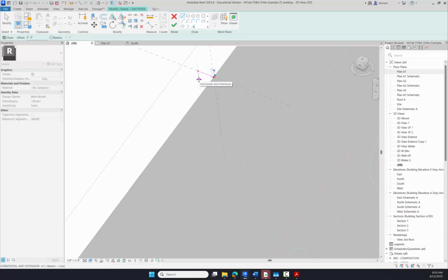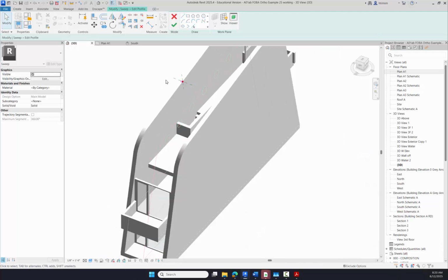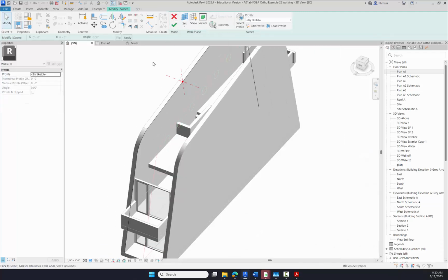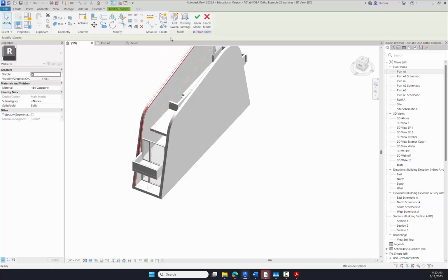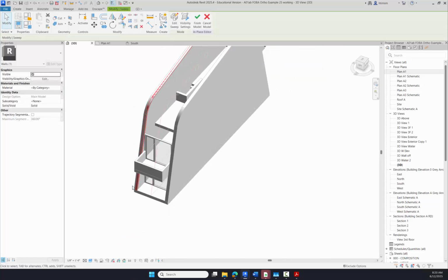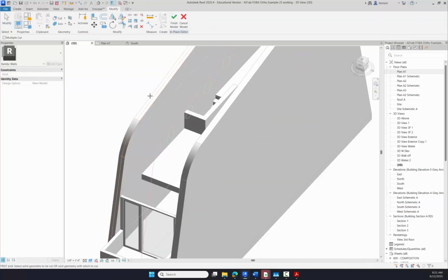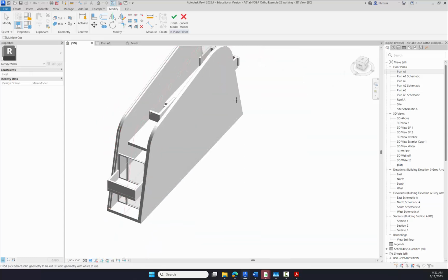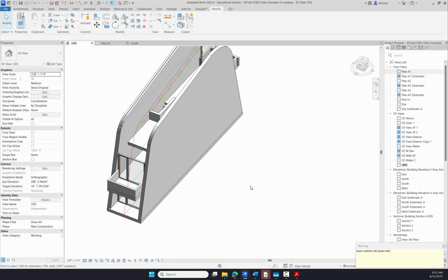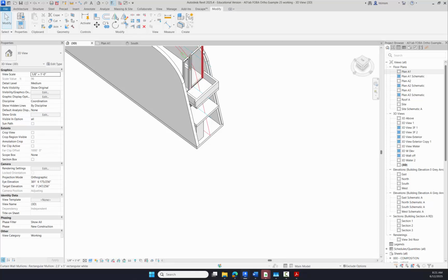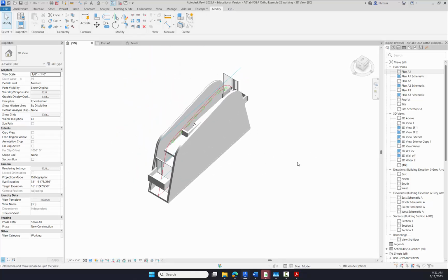I'm going to make one that's 6 inches by 4 inches, square, right? It has to be closed. Then if I hit check, it'll finish that profile. And if I hit check again, it'll sweep that profile around the edge of the path. Then I want to make sure that profile is selected and change it to a void, and then cut from the wall. All right, and then I can finish the model. Now it's yelling at me because it's going through a wall over here, but it doesn't matter.